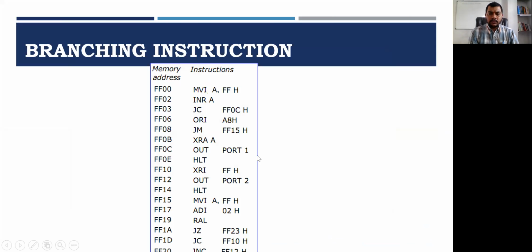So this is one of the examples which I have loaded in this presentation, which actually shows where we are going to use these instructions and where they are jumping. So we have to show the arrow in the flowchart, so that we should understand that the jump is from here to here, right? So we will be using a kite sort of shape for these jump instructions. You might go through the notes where we can see how the jumps are being drawn in that flowchart. So for a jump, we have to specify the address where this jump is there.